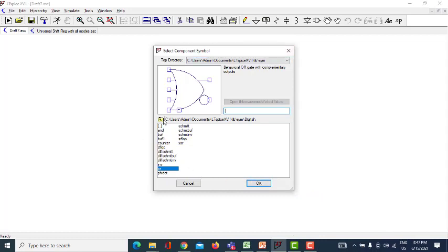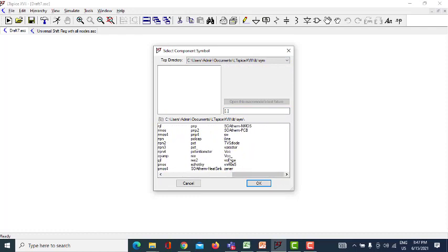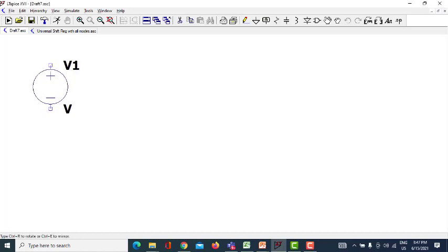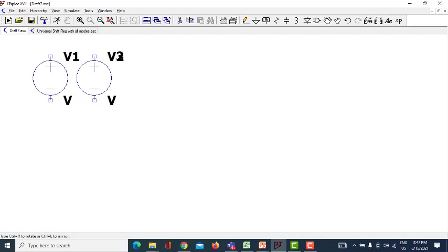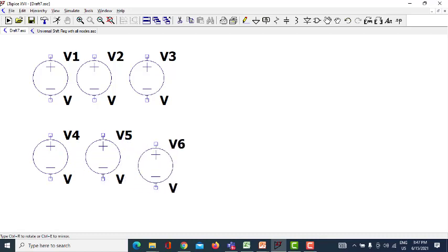Let me take this voltage pulse for defining all these signals. So I need 3 inputs, shift left, shift right and parallel mode. Okay, and then I need 2 for mux and 1 for my clock pulse.